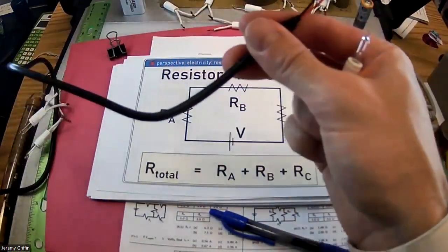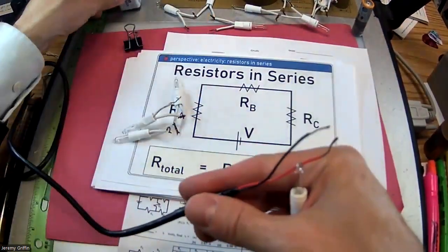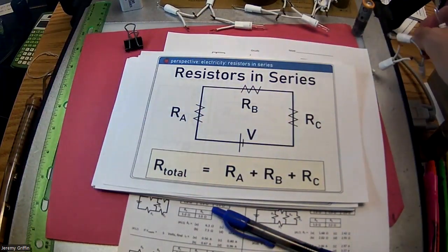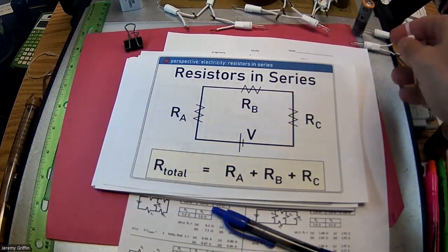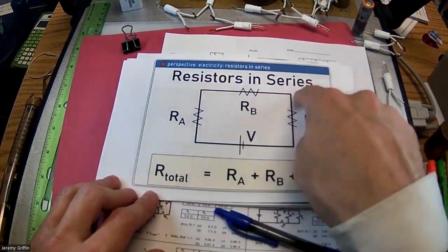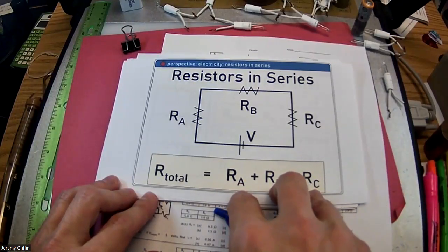So there's 5 volts across these leads, which is about half of this guy, which is 9 volts, right? But you saw they're really dim. That might be an indication that the resistance is building up more and more. If you put resistors in series like this, where they're in a row, then the resistance builds up, and all you have to do is add them together.